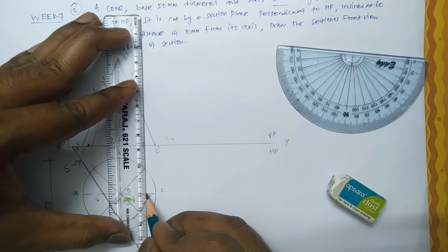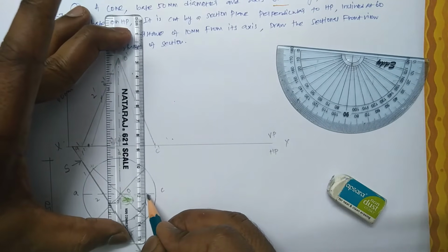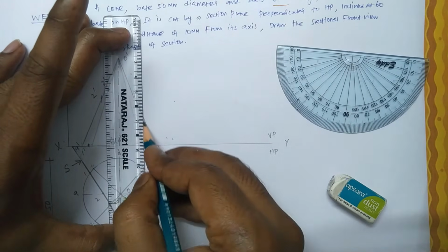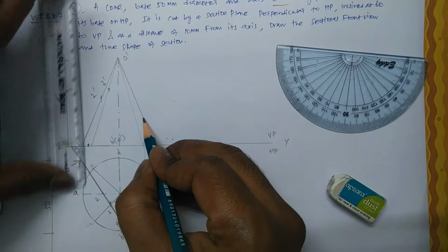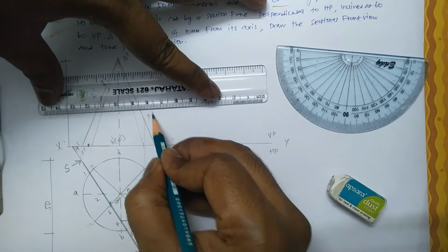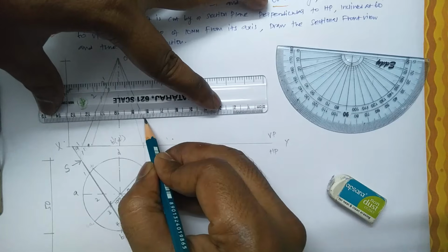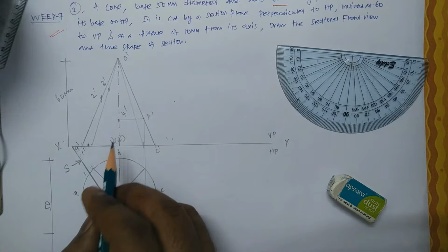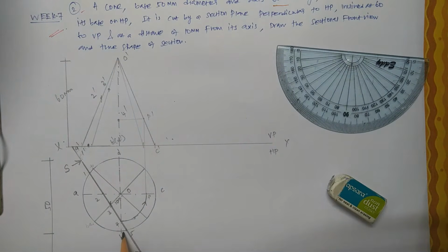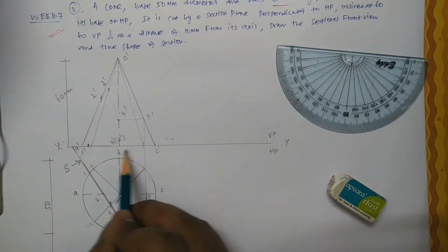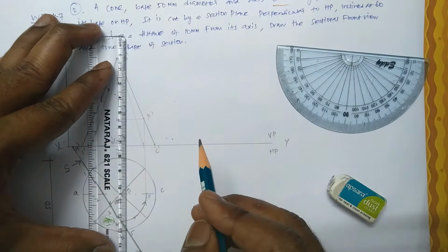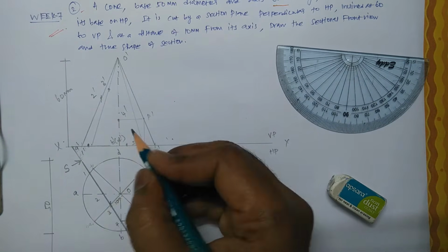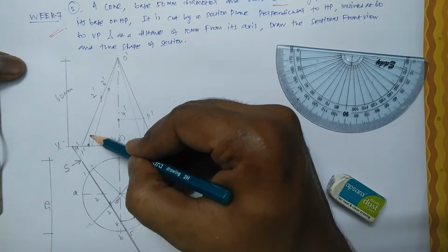So erect a vertical line that must be parallel to this. It meets here. So from here you just make one turn, this is P dash, make a horizontal line. So this is a point 4 dash, okay, and 5 dash is nothing but it is between B to C and it is in the horizontal B to C. So when you are erecting, this could be 5 dash. Now you just connect by a smooth curve.